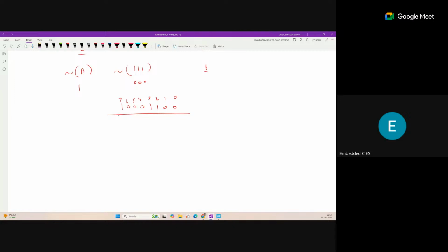Suppose we have these bits in some register. Say in register R1 we have these bits predefined, but our purpose here is to set this second bit from the right to 1, the high state. So how will we do this? We will find a corresponding value like 0 0 0 0 0 0, with 1 only at the bit which we want to set.